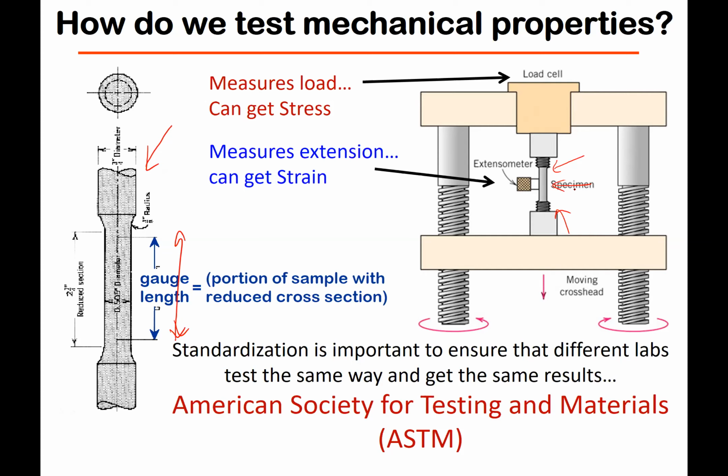They're not as ductile. So engineering ceramic materials where you want the material to fail right in the middle there is actually extremely difficult, because either you clip on the ends of the specimen, or you have to screw on. As you can see here, there are screws. So you can screw the specimen onto the load frame.